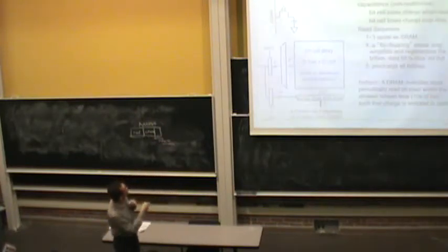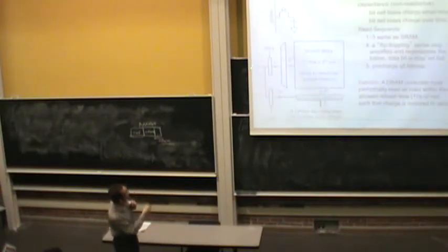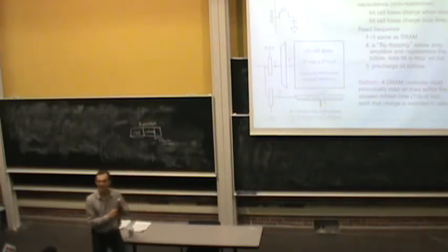Okay, DRAM is very similar. Your bit cell array is like this. Your cells are essentially 1 transistor, 1 capacitor cells. Now here I've shown you a little difference. Here we've supplied both the row address and the column address at the same time, if you will, to the array, and we've decoded the column address. Well, you could have an address register here. You supply both of them at the same time. In most DRAM chips, you first supply the row address and initiate an activate, if you will, and then you supply the column address. So you divide N versus M. Anybody guess why?